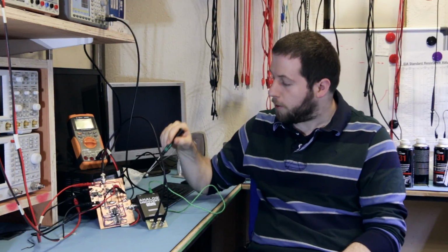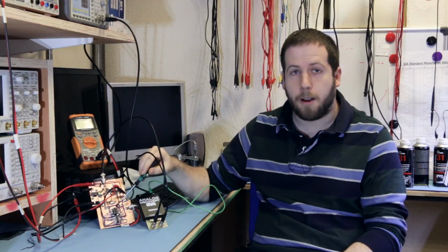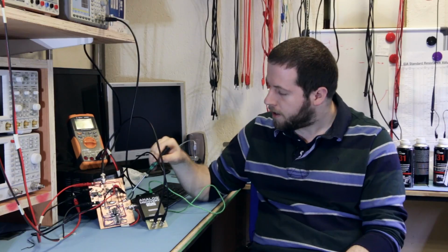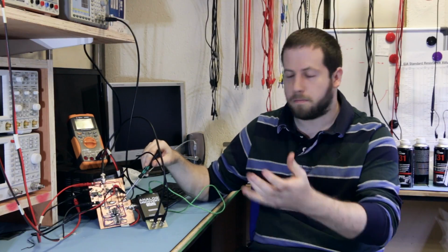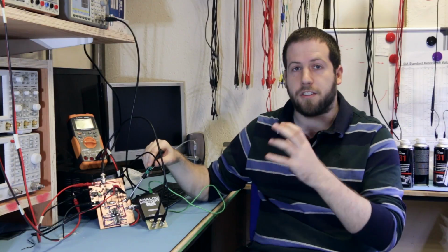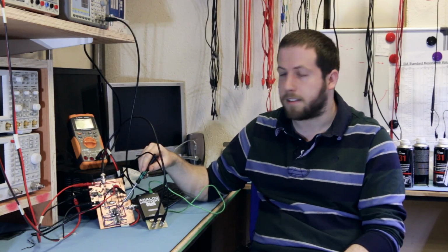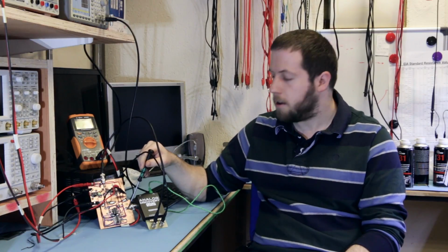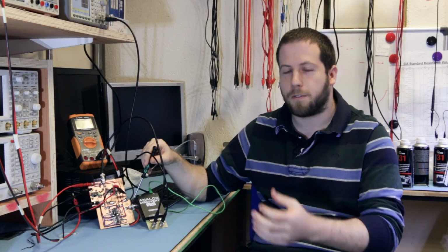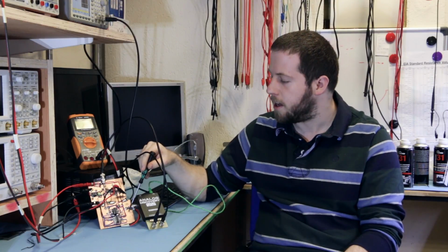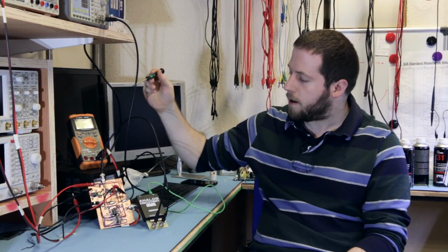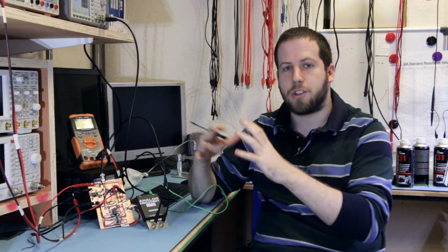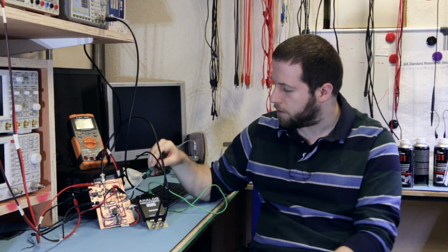So we've taken the filter from before, and as you see we've just modified this lower part of the circuitry, so it's now got multipliers on instead of the switches that we had there before. The rest of the circuit is very straightforward, it's just some resistors and bits and pieces to set up the multipliers so they've got the right gain, which in this case is times 1. We've taken the input signal here and modified that, so now instead of the control signal for the switches, that's now the control signal for the multipliers. I've just got this connected up to a waveform generator, feeding in a DC signal, so we can just control that DC signal and change the gain and therefore the cutoff frequency.